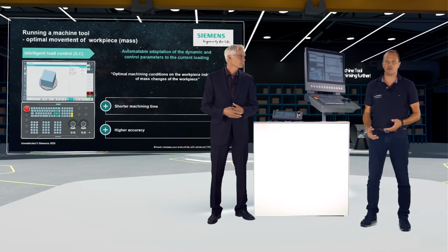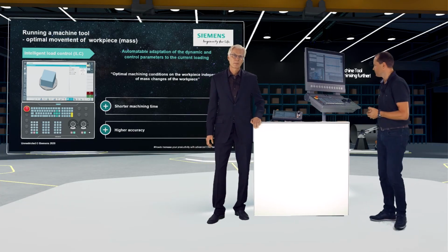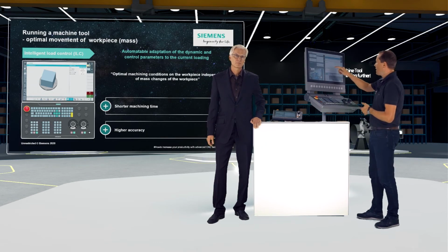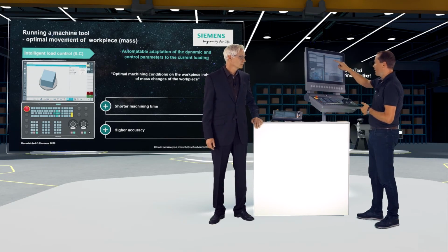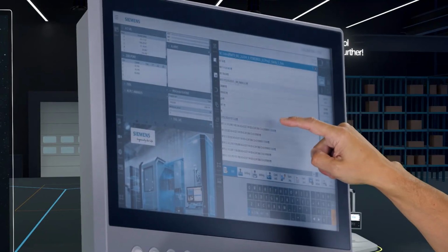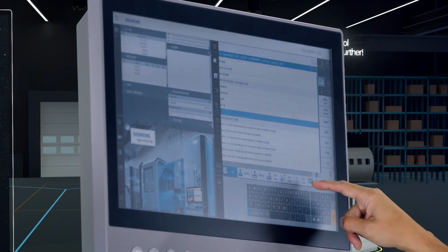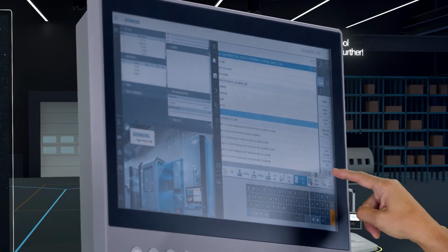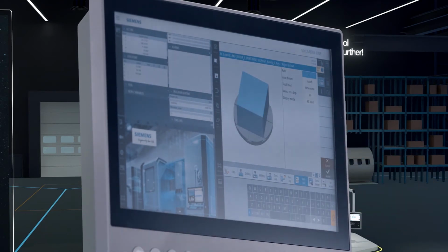In this case, to show the best benefit of ILC, I use a 5-axis part program. The part program is a 5-axis simultaneous part program, where we already activated our high-speed setting cycles. And before real cutting, I have a new function called ILC, under various, adjust to load, cycle 782.